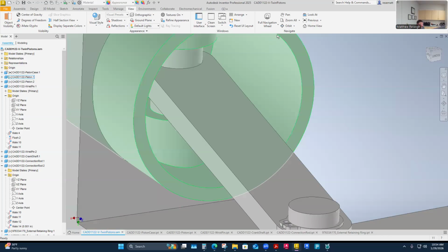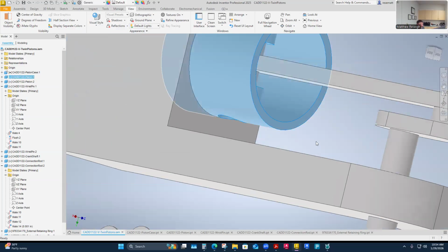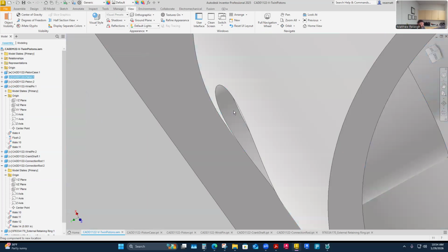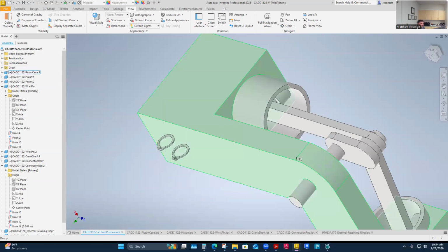And then I'm going to take this piston and figure out, for that internal snap ring, where this face is to there and space it off some tolerance, and then put in my snap ring that goes internally here and cut an internal groove in the piston to accept the internal snap ring. And then I've got to assemble all that stuff. And yeah, that's what I'm going to do.